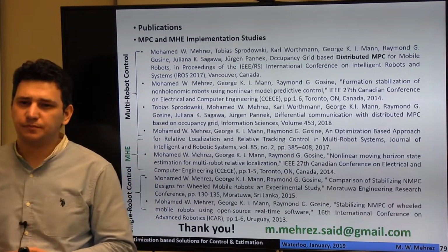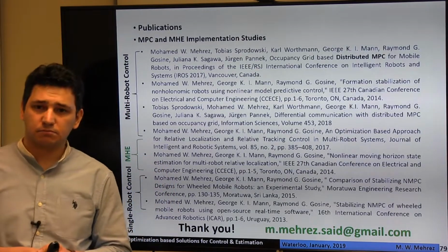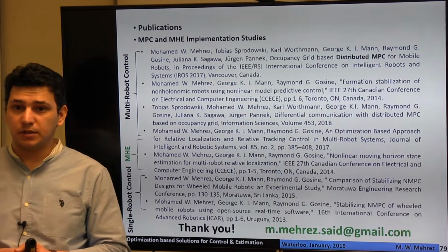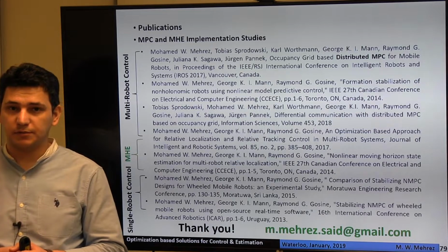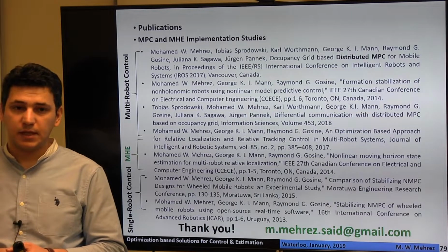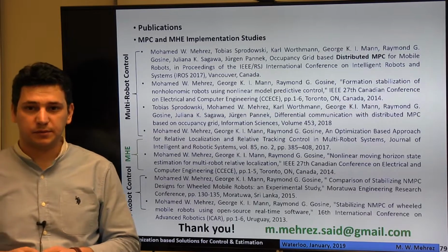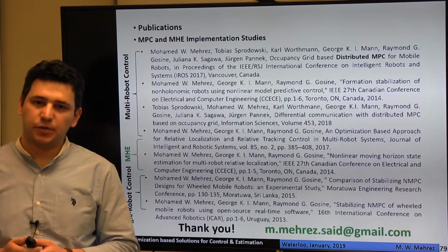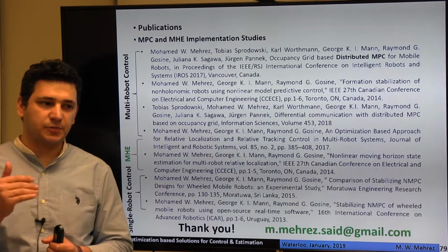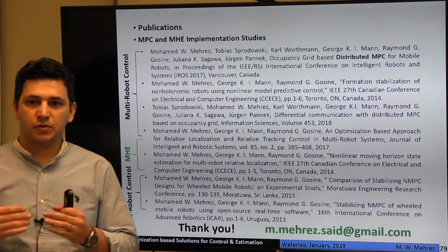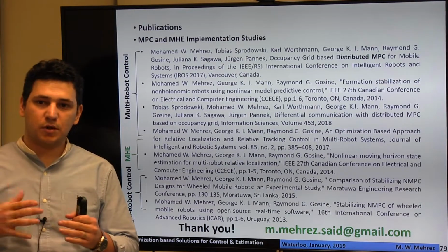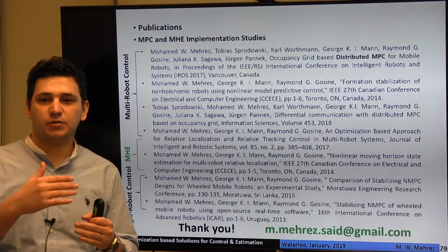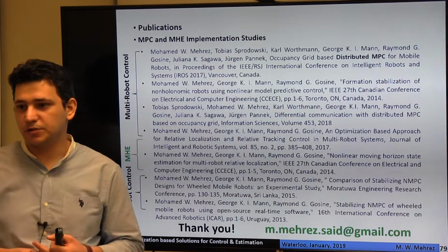My question is, is it possible for MPC to have constraints that are changing? Yes, definitely. But then timing is important, the timing of the change. Because when you do prediction, you do this at predicted time steps. So if you want to avoid obstacles that are moving, you should know where they will be in the prediction, or the predictions of their future motion.